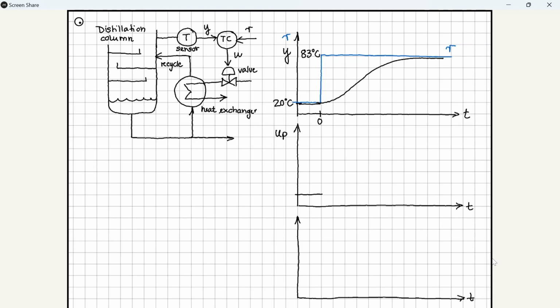At the beginning, the P controller will apply a large signal to the valve because the error is large. But see what happens as we get closer to the steady state. The P controller stops acting altogether.